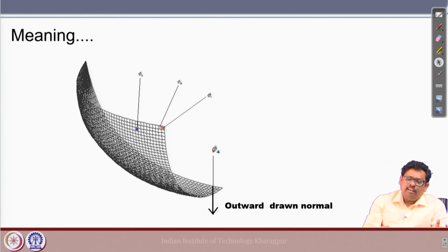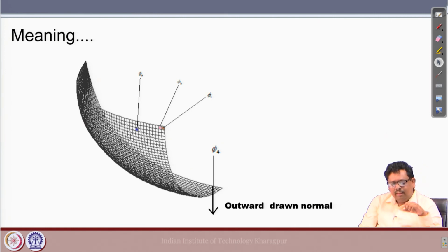I think we are going to discuss later on, if that body has symmetry, then you do not need to model the whole thing. You can model one part of it, and then you can use the symmetric property, and you can get all the other things anyways. So, in case of a sphere only 1/4 is good enough for modeling.